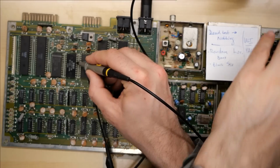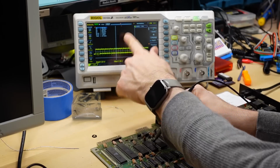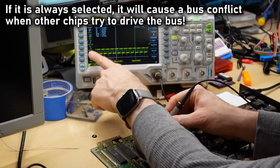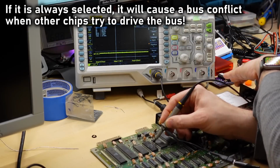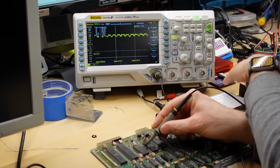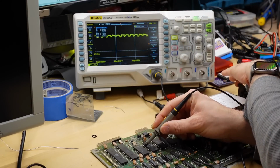If I move to the kernel ROM and we turn it on, it's always low. And that would mean that this chip is always being selected. Now it's not completely at 0, but this is probably 0 enough that it's always being selected. And if we look at the BASIC ROM, it looked normal there. You see how when I first turned it on, you saw some ups and downs? Now it's just sort of stuck, but that initial part looked normal.